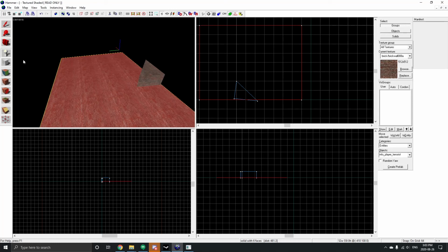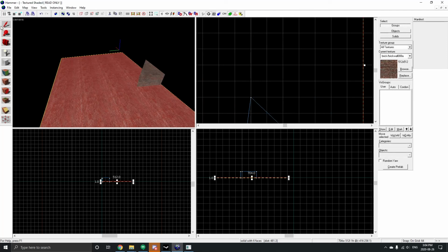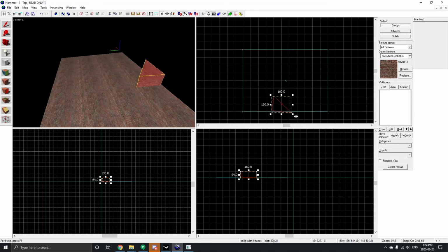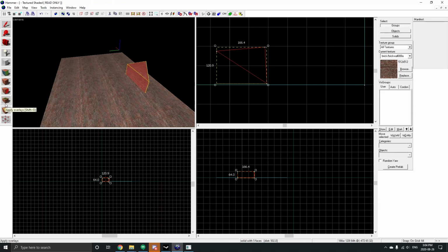It's very simple, and some things I found difficult, and I couldn't see explained anywhere, is actually how you rotate objects. So, if we select one here, how you rotate this object is just click it right here, and then the borders should be empty circles, and then you can just rotate it all you want. So that's a little tip that I found, and I realized that a lot of new people to this program aren't familiar with that, actually. I guess it's not intuitive, but yeah. That's pretty much everything you need to know for this program.